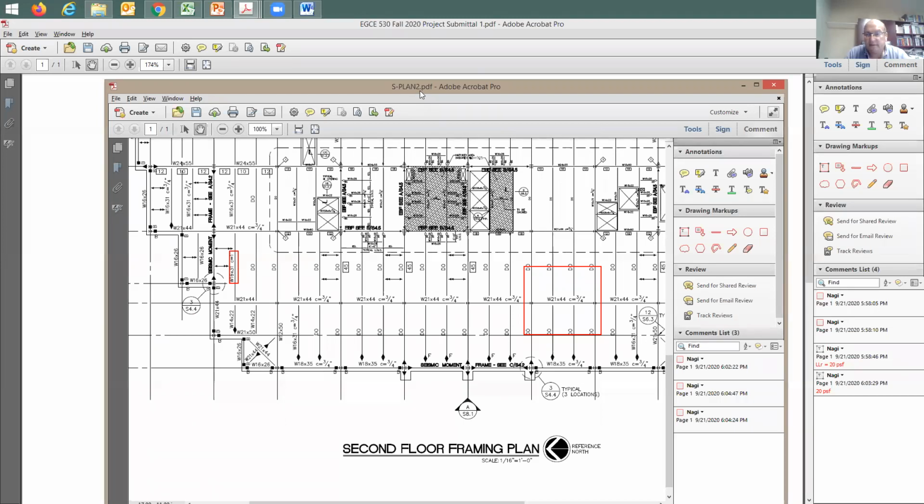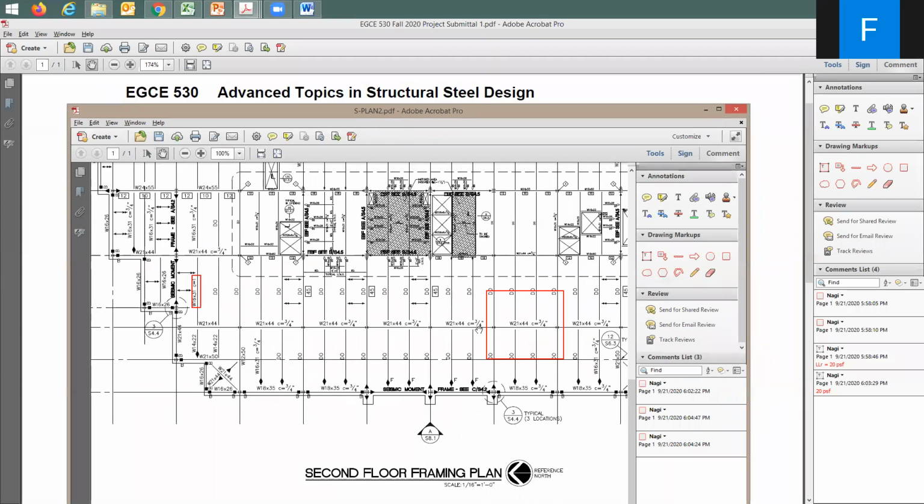Professor, I have a question about the girder. So when I take the maximum moment, since there are two perpendicular beams on top of the girder, is it going to change the moment equation? Yes. Is it because it's a composite body? It is going to change it. So it's going to be 2 point loads instead of a uniform load.